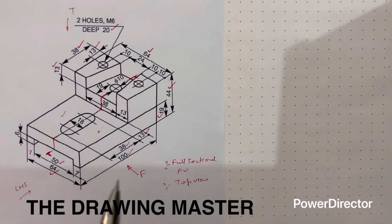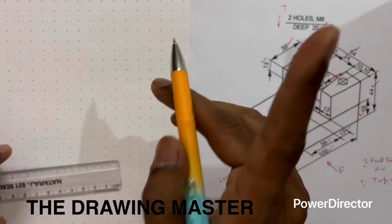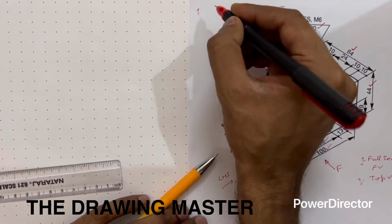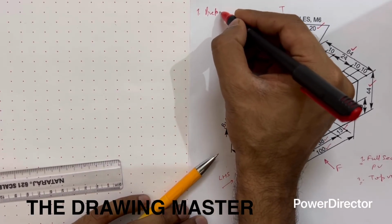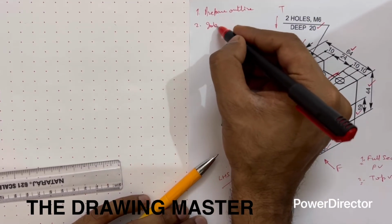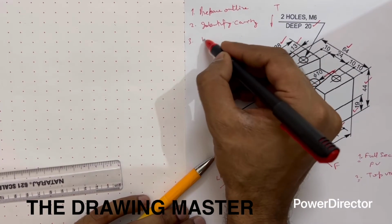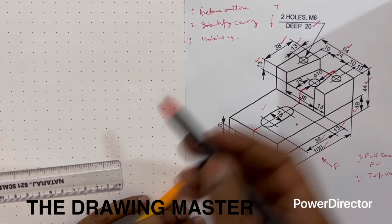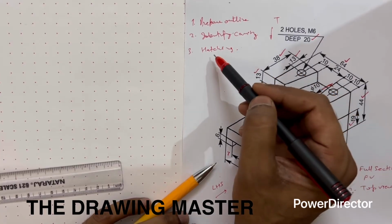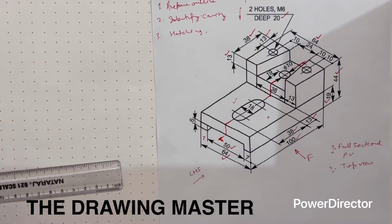First we'll draw the outline. See here, there is a very simple trick. You have to remember only 3 simple steps for the sectional view. First one is prepare the outline, then identify the cavity, and third one is hatching. Only 3 simple steps are there. Prepare the outline of the object, identify the cavity or hollow part, and the third step is hatching. So let's prepare the outline of this object. It is simpler than the orthographic.